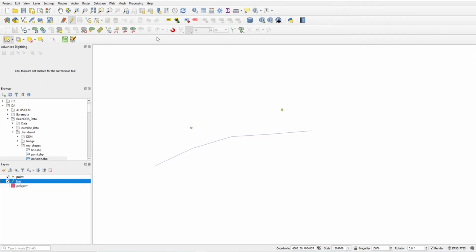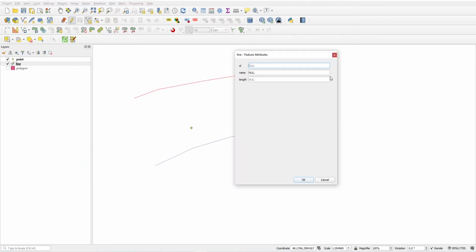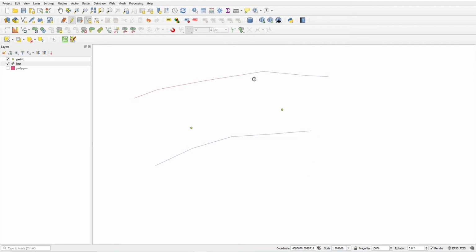I'll tell you later about the snapping toolbar. First go with this layer. So I'm just turning off this one. If I want to place one line, just click and this one. You can fill the values here and OK. This is how you draw a simple line.